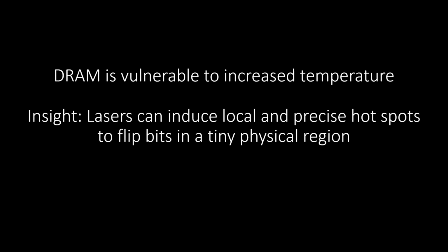The factor that we add here is use lasers that can induce local hotspots, right? These hotspots are localized to a particular physical location, a very small location, and we can induce bit flips in this specific physical location. And our hope is that by using this localized heating, we would be able to reverse engineer the internals better, and also explore some new type of vulnerabilities. So this work is majoritarily focusing on how to develop this methodology.